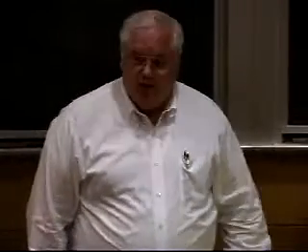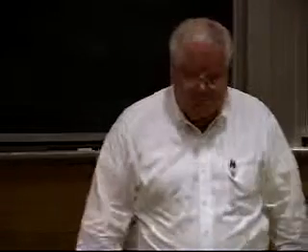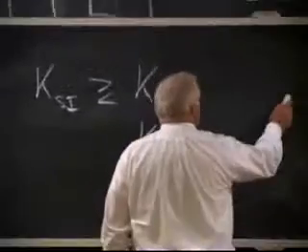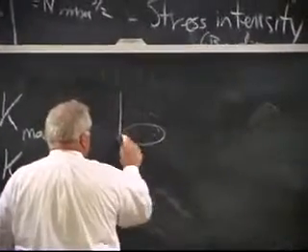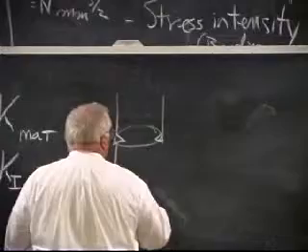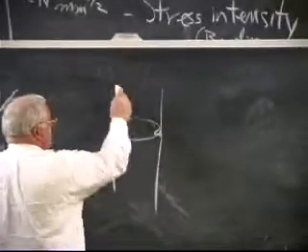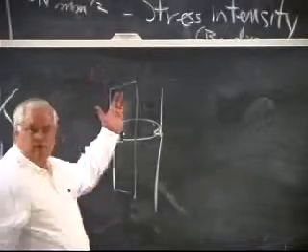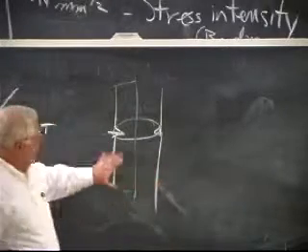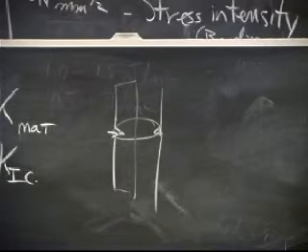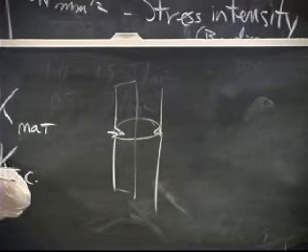Okay. Other questions? Yep. We have a rod, and it's a circumferential score. How do you measure A? Is it the length of the score around it or the depth of the score into the rod? Oh, I'm talking about circular rods. So I've got a notch like that, but it goes all the way around. Well, it's the depth in. You basically take a plane out of this, a radial plane, an RZ plane, and you just look at it as if it looks like this. So A is that. It's not going all the way around. That's what I thought. Okay.